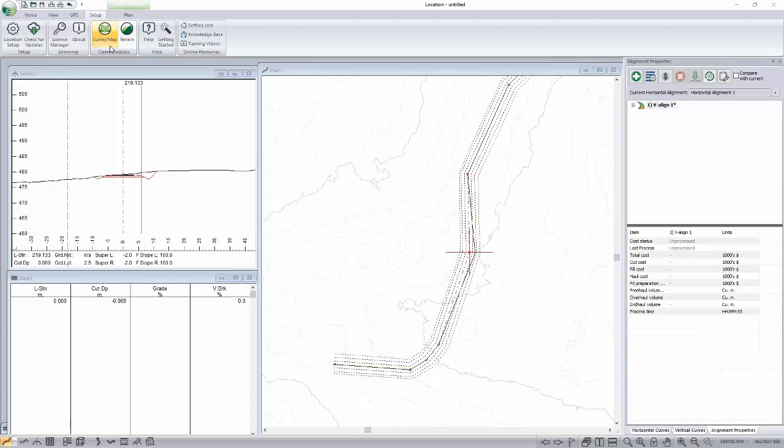will separate them if you're lucky. LAS is typical of this. It'll have both ground points and other points in it, and you can select those at import time. All we need for RoadEng is three-dimensional ground points. That's it, nothing else.